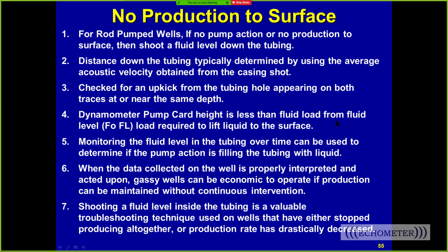But be cautious, because if you have an incorrect plunger size, then the FO from the fluid level is calculated based on input data, and you could have a 1.5-inch pump in your well and a 2-inch pump entered into your software, and the software will calculate a much higher FO from the fluid level than you actually measure, and you might think you have a hole in the tubing because your pump card is not tall enough. But you need to confirm it with fluid level shots and pressure testing your well, and not pull your pump because the pump card height doesn't equal the FO from the fluid level because someone typed in an incorrect plunger size. So be cautious about this right here.